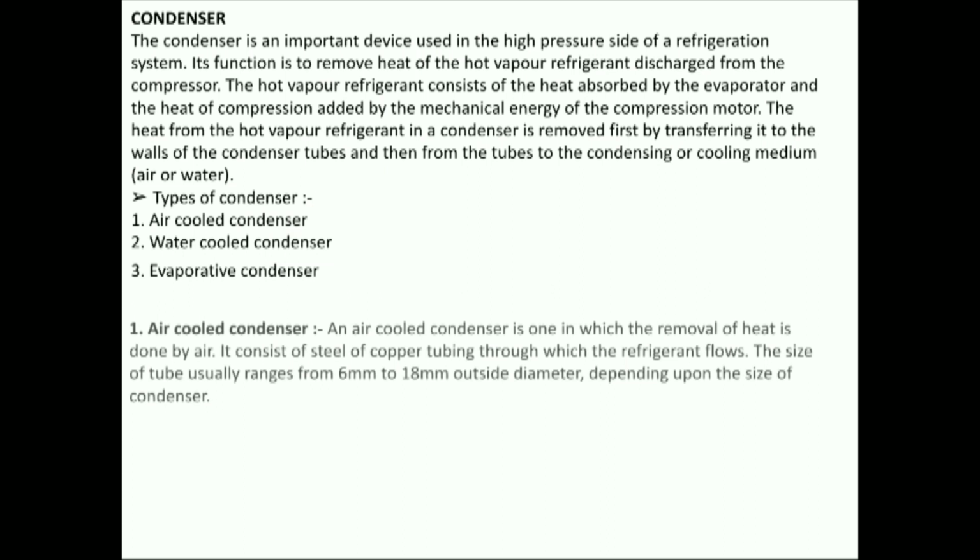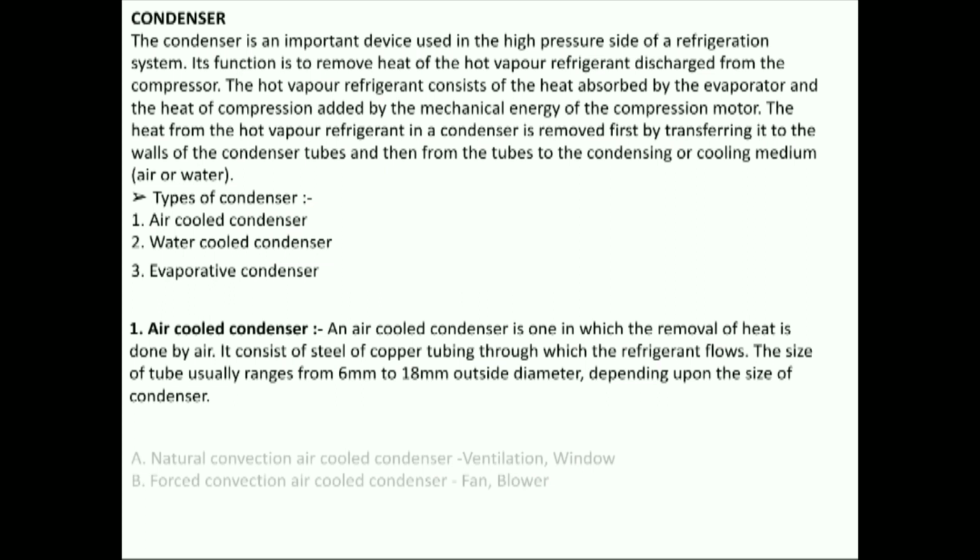The heat from the hot vapor refrigerant in a condenser is removed first by transferring it to the walls of the condenser tubes and then from the tubes to the condensing or cooling medium, air or water. Types of condenser. 1. Air-cooled condenser. 2. Water-cooled condenser. 3. Evaporative condenser.